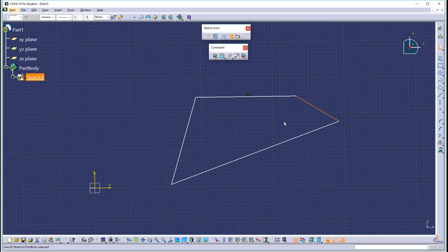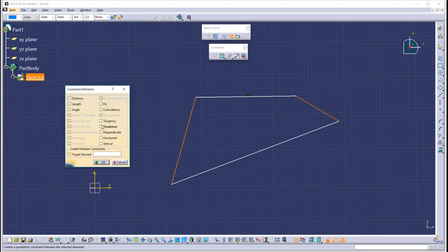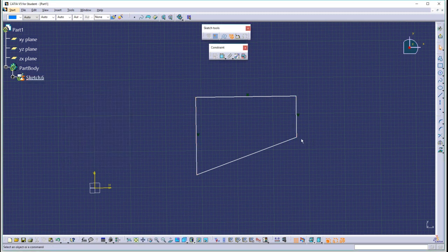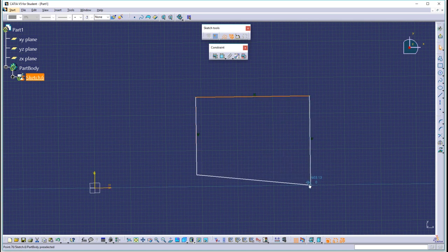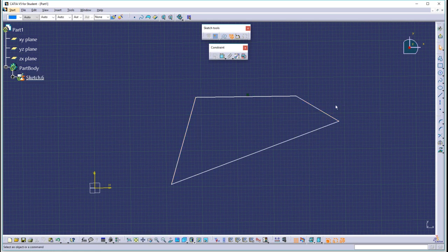I can pick this item, Control key, pick this icon, and now pick here, and let's pick vertical. Now both of those are vertical, and they're constrained to be vertical. Now this line is not. Now I'm going to Control Z to back up out of this a little bit. Now we don't have verticals on there anymore.